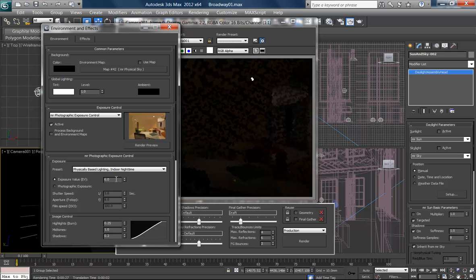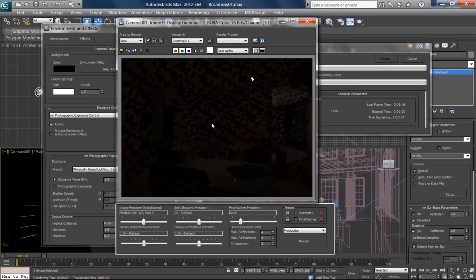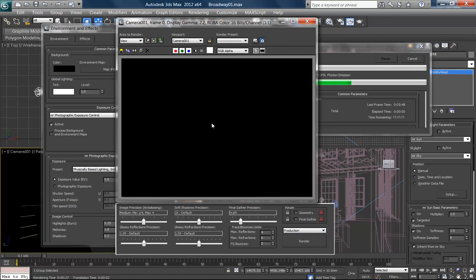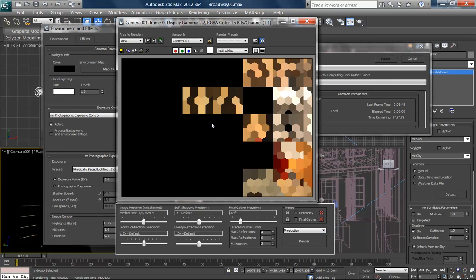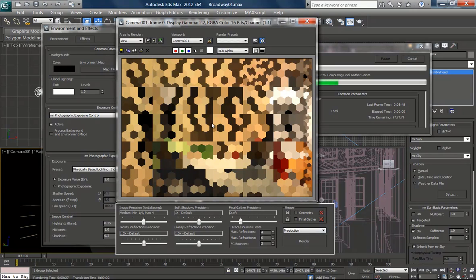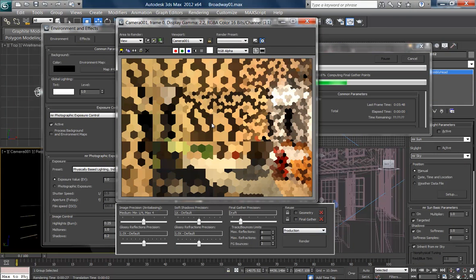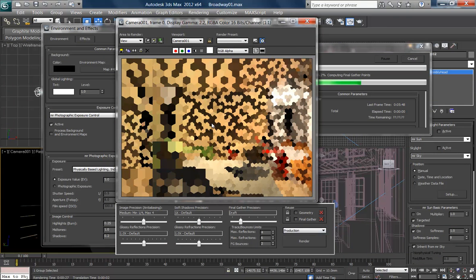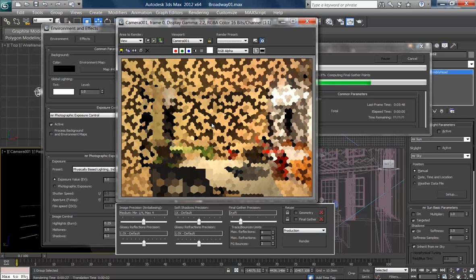Anyhow, you can see here I've got the exposure value up to 6. That's maybe a little high, so down to 5, or no, 4's too low, so 5 is probably about right. Okay, so I'm going to render again now, and you'll see it's going to be much, much brighter. Now, again, this is just with the lights as they come in from Revit, so I haven't done anything with them yet. But what I want to do now is really get in and do some things with these lights, because it's not very interesting to just have these things you can't adjust.